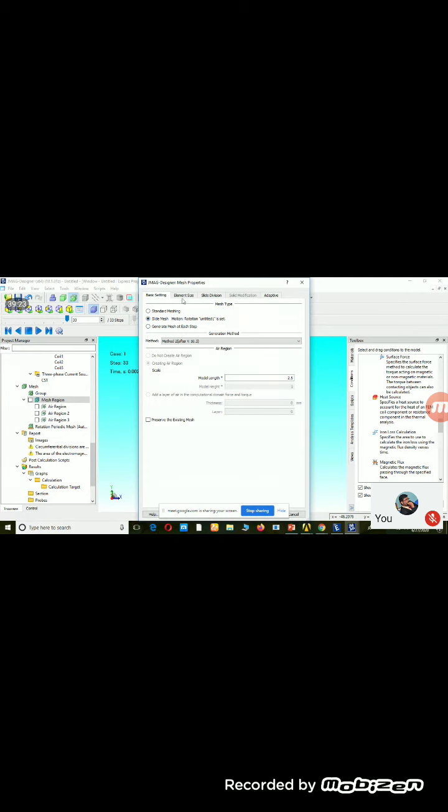And when you go for the element size, it is set automatically. Suppose if you are setting the element size, just set it as 2.5. Next one is slide division and solid modification. So all these things you have to give if you are going for your own diagram, right?